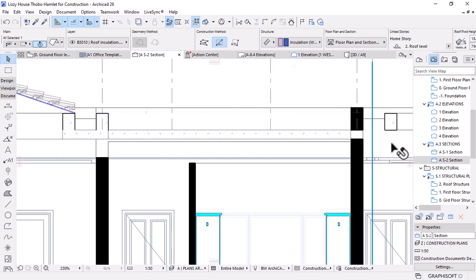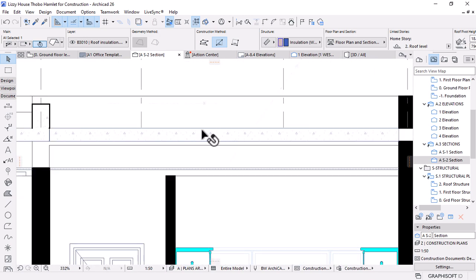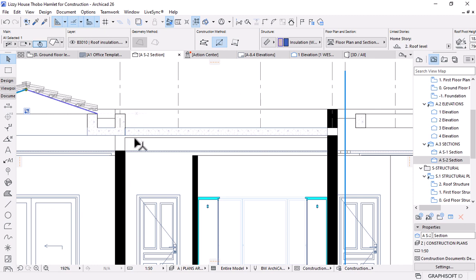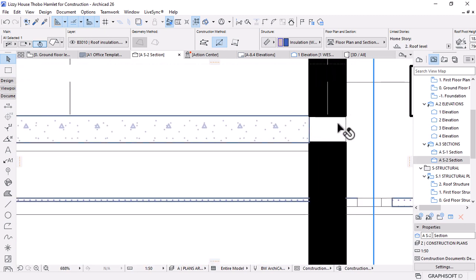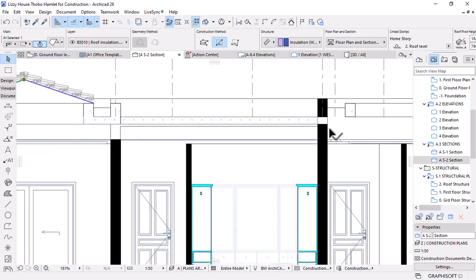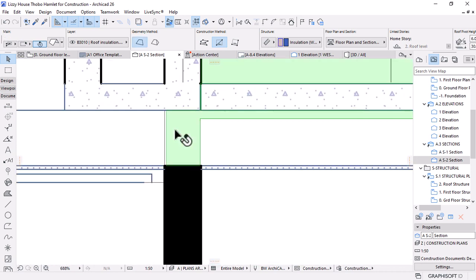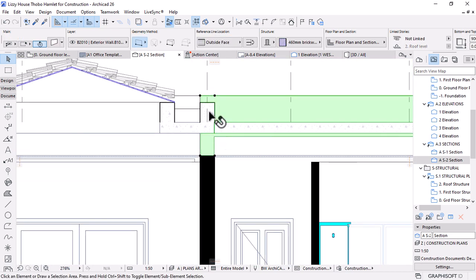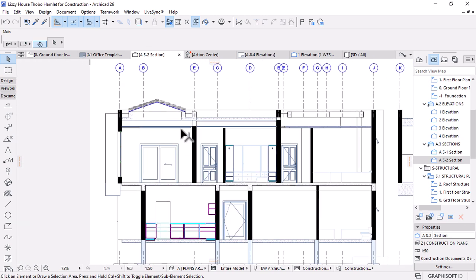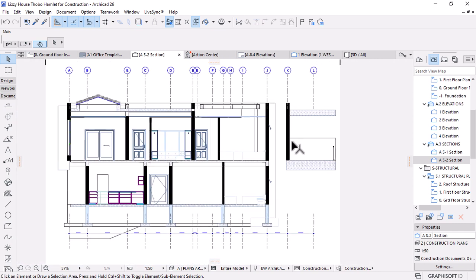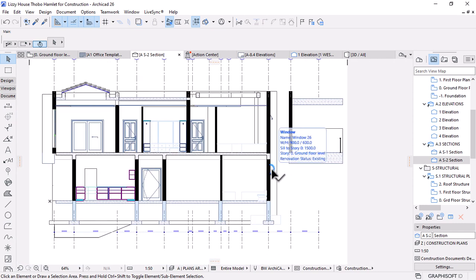And then we have the roof slab that needs to be detailed. We also need to show the collection of water from here. We need a detail for that. There is an issue of pens as well. Here we're missing a beam again. I think here we're missing a beam too. So this has to go all the way like that to be continuous. There are quite a number of things that you would track, like I'm saying.